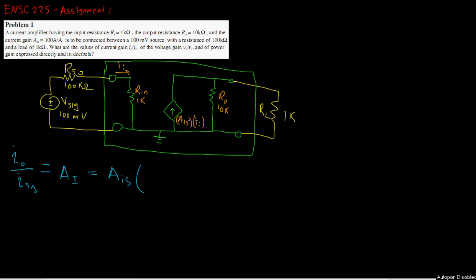So we're going to take this open loop gain and we're going to try to multiply it by something that will adjust this open loop gain based on the fact that we have this R_L hooked up here. Remember, everything in the green box is internal to the amplifier. So the only current that's going through the load is the only current that we can measure from outside the amplifier. So the current going through the load is what really matters.